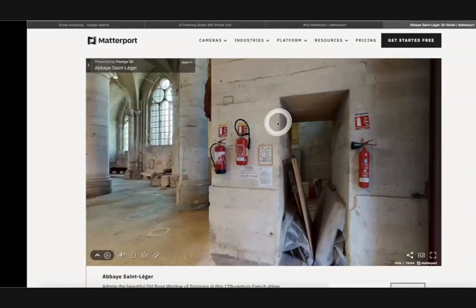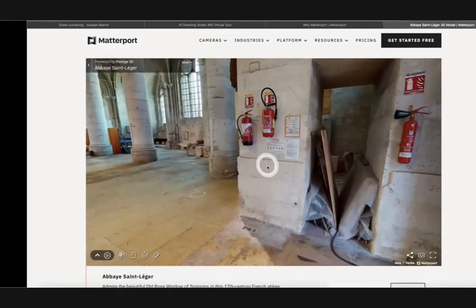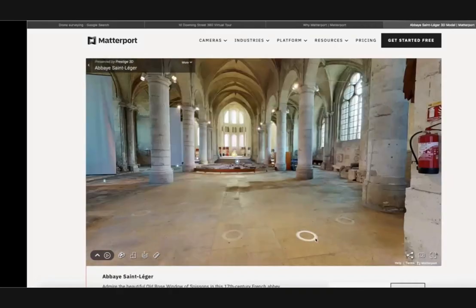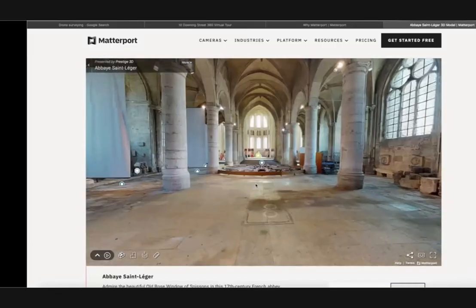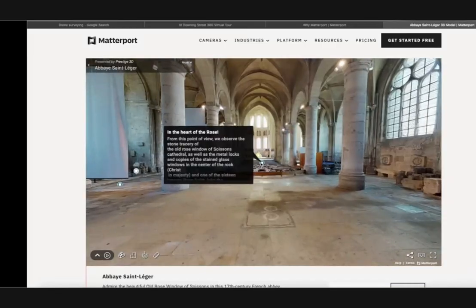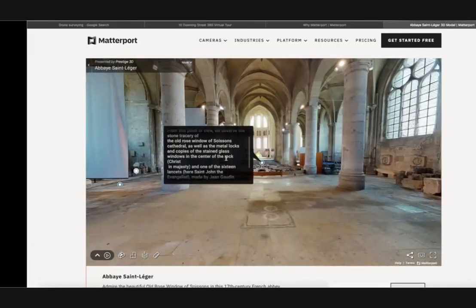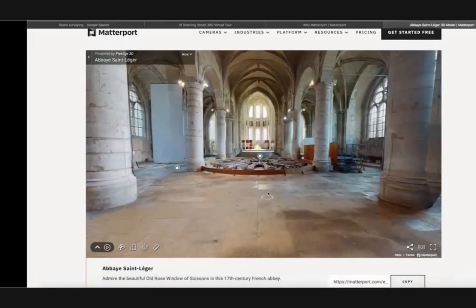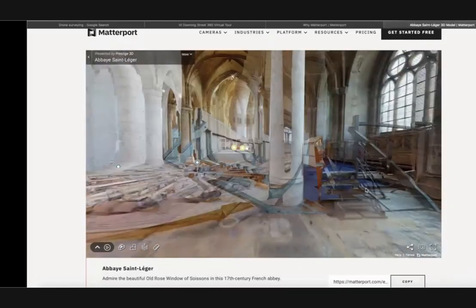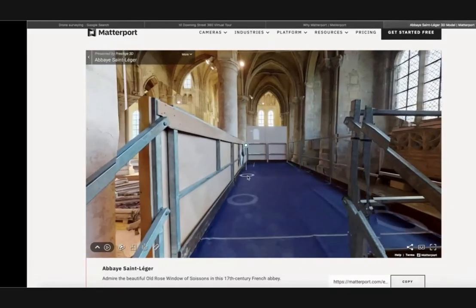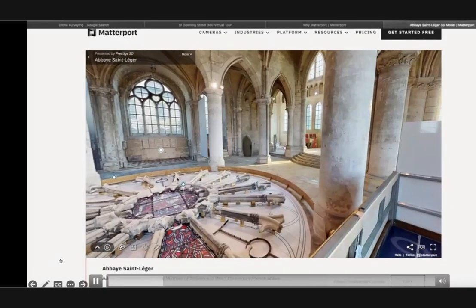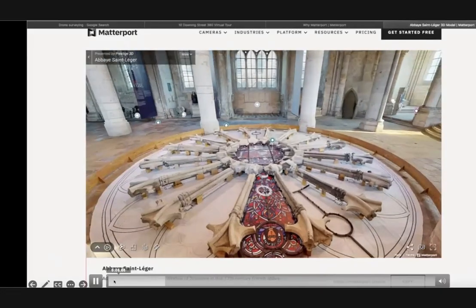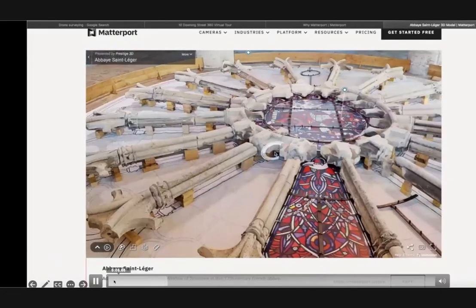With a Matterport, I wouldn't trust any measurements on it. They've done a big thing with a lot of similar products, where they say that you can provide floor plans off it now and measure building surveys, but the quality of the actual scanners is pretty poor. Even the latest one, when we test it versus a proper laser scanner, you'll find a huge amount of drift.